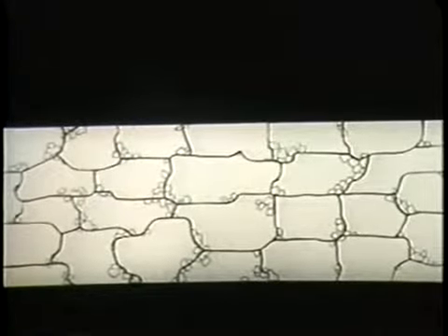The grains are now elongated and oriented in the direction of flow. Beyond this point, severe cold working may lead to more violent deformation, in which fragmentation and crushing of the grains occur. The total effect is to increase the metal's strength and hardness.